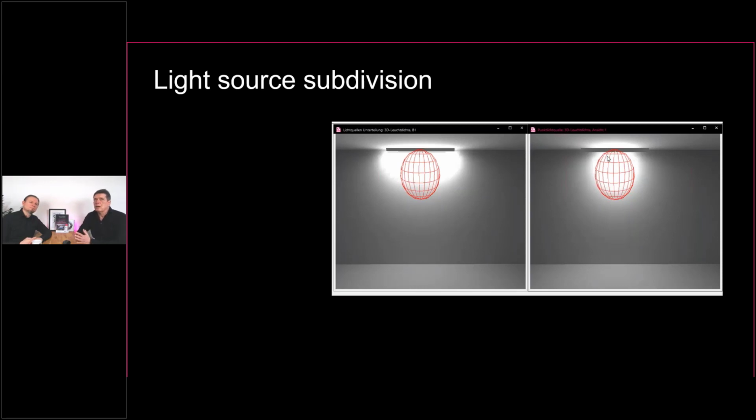Because you must realize that the geometry which is displaced from one luminaire and the LDC is the same thing. During the calculation, the geometry of the luminaire itself, where the light is going out, must be ignored, because it is already included in the measurement in the LDC. For that, we should not take the geometry of a luminaire itself into account for the calculation of the shadows.